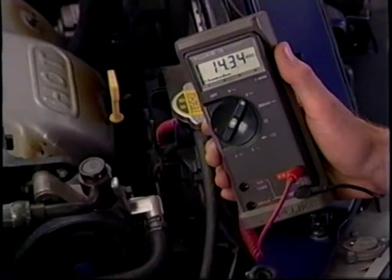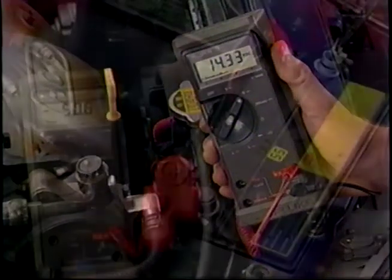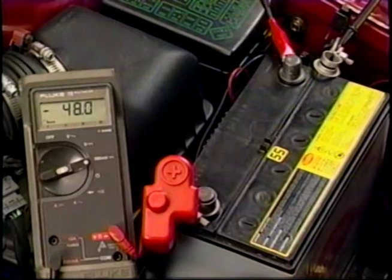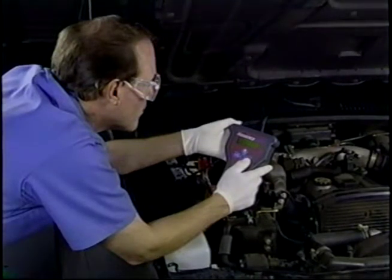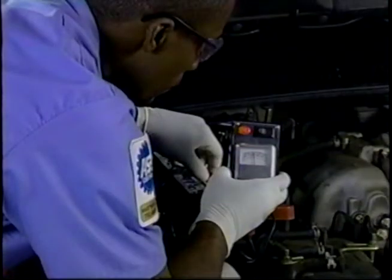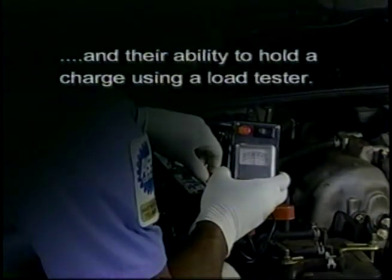The operation of the engine electrical system can impact the vehicle's drivability and performance. Low battery voltage can cause low current in the primary ignition circuit that can cause lower than normal firing voltages and engine misfires. Battery testing requires extreme caution, and you must use safety glasses, gloves, and protective clothing when charging and testing batteries. Batteries should be tested for their state of charge with a hydrometer or voltmeter and their ability to hold a charge using a load tester.